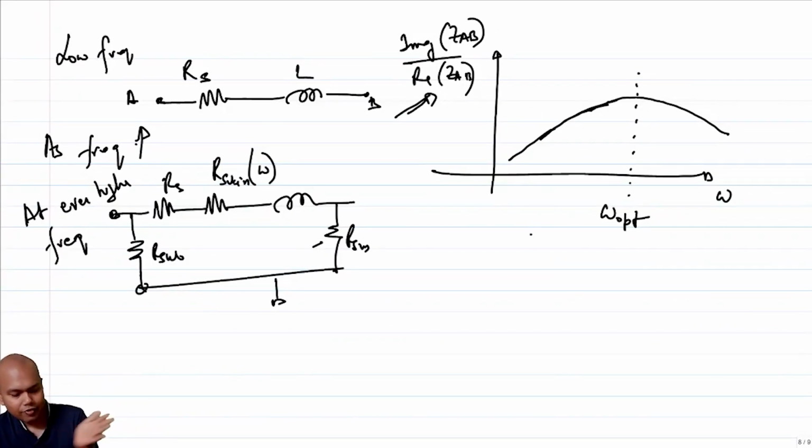on the left side of it, clearly, I have not maxed out the value of the inductance, the effect of the inductance, or on the right side of it, it looks like I have more and more loss, right? So in a way, once you have this inductor model, you have to characterize the inductor, this effective model, not only the inductance, plot the imaginary versus the real part versus omega, and then see where this maxima is, and operate the inductor around the maxima.